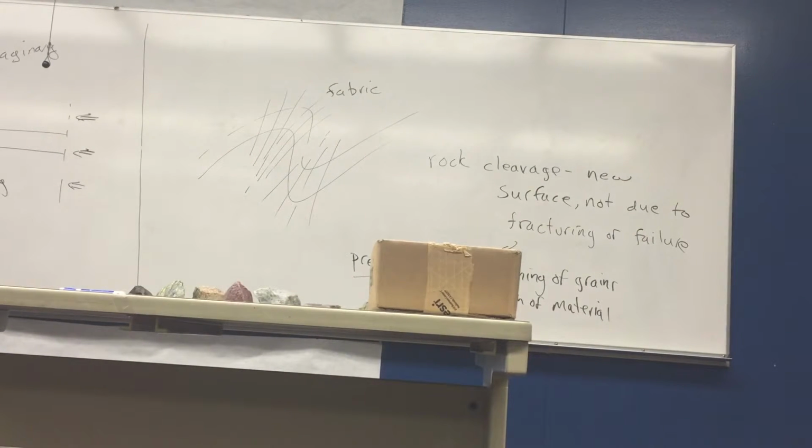If you look at the back side, you see some lineations here. This is a type of cleavage. The best way to look at it is let the light shine off and you'll see a zone that has these short lines spaced out, zones that don't, and again, zones that do here. Those are pressure solution surfaces.